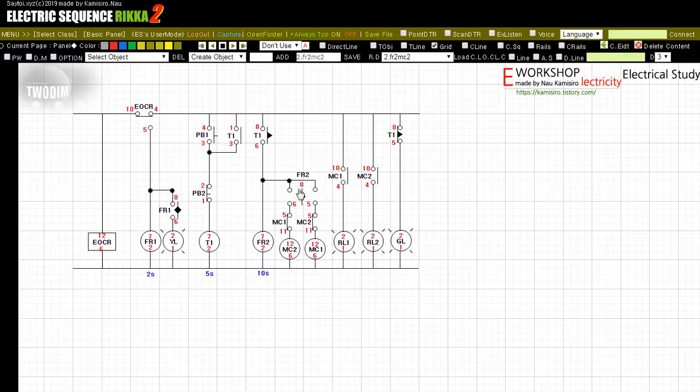In the electrical sequence drawing, we will first omit the section on the main circuit. You can understand the motor's forward and reverse motion and engagement if you have fully understood the motor's operation in the previous time. The overcurrent relay is powered by a fuse. At overcurrent trip, ON and OFF are repeated for 4 seconds and 2 seconds each by the action of flicker 1. When push button 1 is pressed by the user, the timer is powered up, which is then self-maintained by the timer's working contact A.